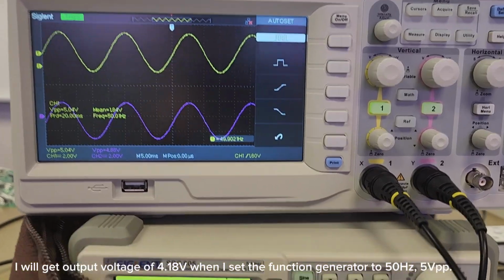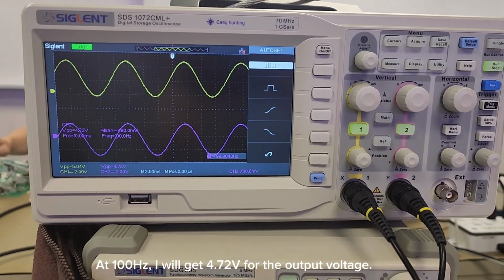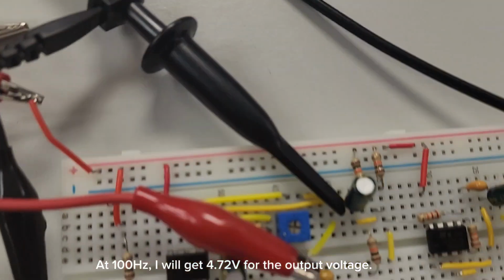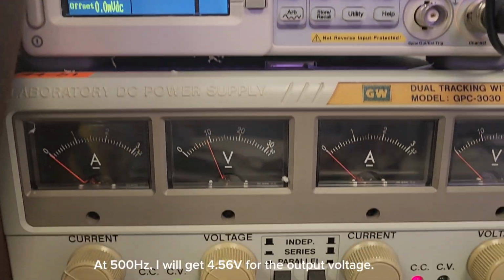I'll get output voltage of 4.8 volts when I set the function generator to 50 Hz at 5 volts peak to peak. At 100 Hz, I'll get 4.72 volts for the output voltage. At 500 Hz, I'll get 4.56 volts for the output voltage.